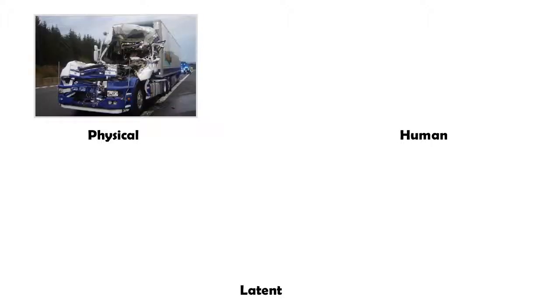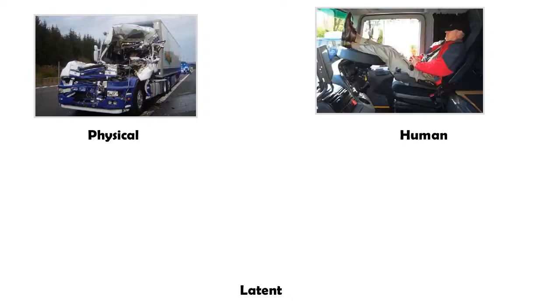They applied the 3 levels of cause. The brake failure could be regarded as the physical cause of the problem. In fact, there had previously been problems with the brakes reported. But why did the brakes fail? History downloaded from the onboard computer showed that the driver had been using the service or foot brake most of the time. He should have been using the retarder and engine brake for the majority of the time.